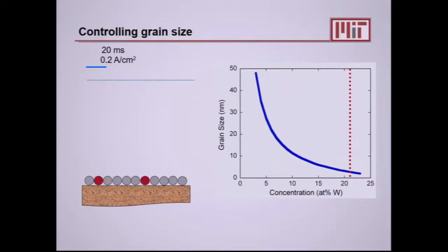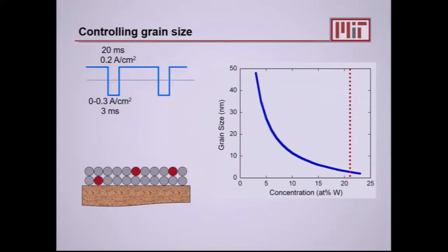Then what I'm going to do is instantaneously, thanks to power electronics, flip the current on that thing. And instead of working in the potentials in the fluid, I'm going to work in the metal. And so for a very short spell, I'm going to actually etch. And I'm going to choose that etching potential such that tungsten is preferentially removed. And now, if I flip the current forward again and put down another monolayer, that's going to get preferentially backfilled with nickel. So he just runs this process, and you put in a pulsed waveform, and you run it for, you know, an hour or whatever. And at every layer, you do a little sculpting of the composition. You selectively strip out tungsten, and you backfill preferentially with nickel. And as the thing is growing, now you have a net effect of incorporating less tungsten.